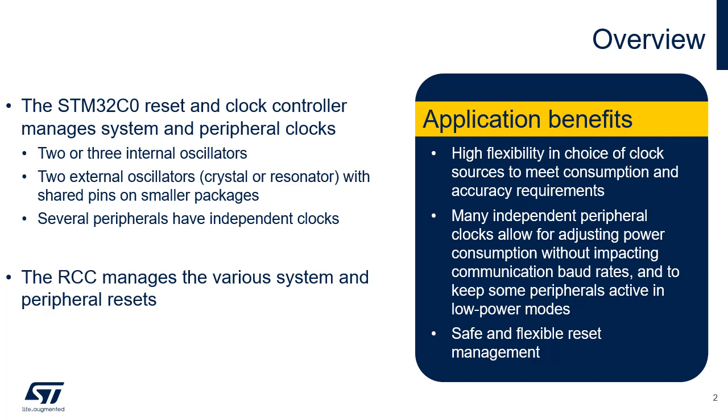The STM32C0 RCC offers great flexibility in selecting clock sources, enabling designers to balance power consumption and accuracy requirements. The independent peripheral clocks allow power adjustments without affecting communication baud rates, and certain peripherals can remain active in low-power modes. Additionally, the RCC ensures safe and flexible reset management.